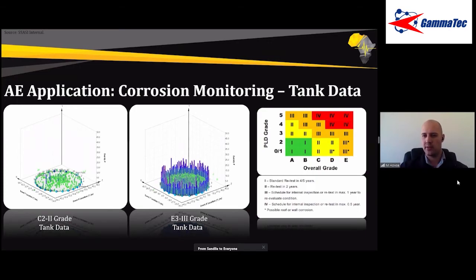Okay, so here we have a good question regarding cracks that have been arrested. If the crack has been arrested and it is not growing when we stress it, we won't detect it. So it is quite often used to actually evaluate repairs.